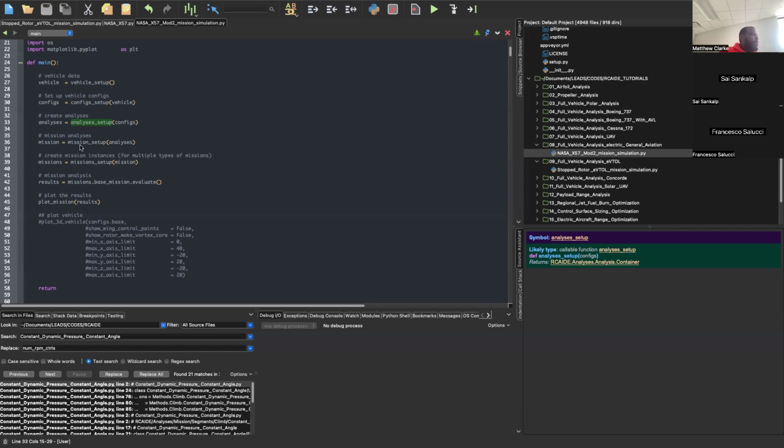How, if you define, for an eVTOL, for example, if you want to first take off and vertically climb up to 10 feet, right? You put altitude start 0, altitude end 10 feet, right? Then you have different transition segments you can define, and then you also have cruise segments, etc.